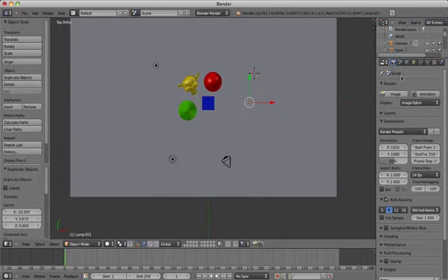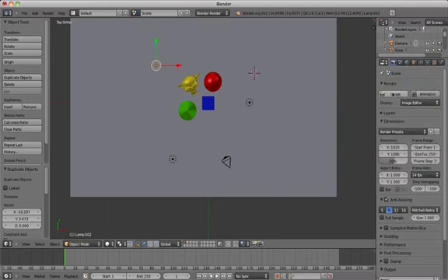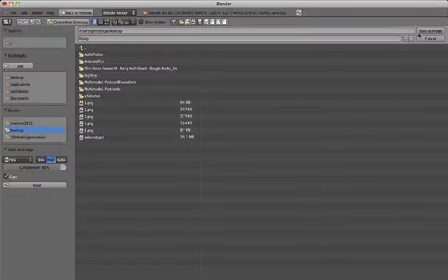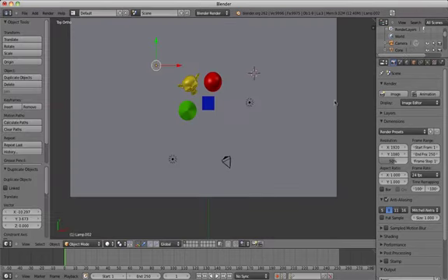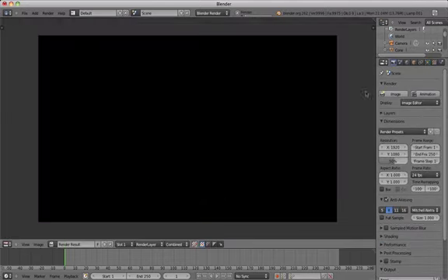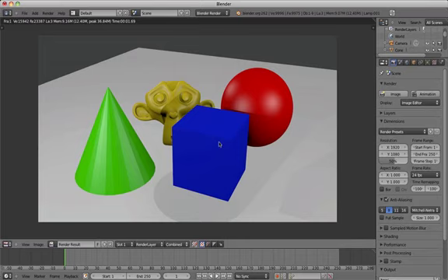If you leave the shadows on for all of your lights, it's going to cast unwanted shadows and make the scene look a little less appealing. So it's usually a good idea to switch off some of the shadows, and it actually speeds up the render time as well. Now render the image and save it as a PNG.